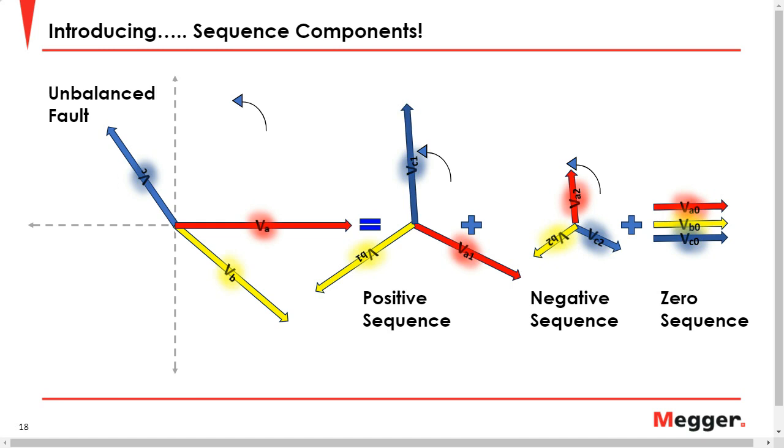Now, we see with the negative sequence, we have our VA and then our VC. So VA passes through the x-axis, then VC passes through, and then VB, so we swapped B and C phases. If the magnitude of this negative sequence was greater than the magnitude of the positive sequence, we would actually have reverse rotation. That motor would rotate the opposite way.